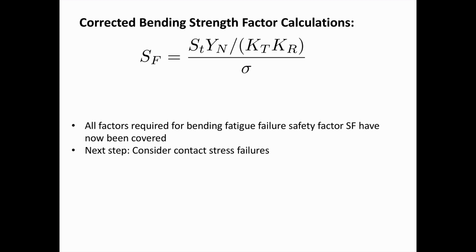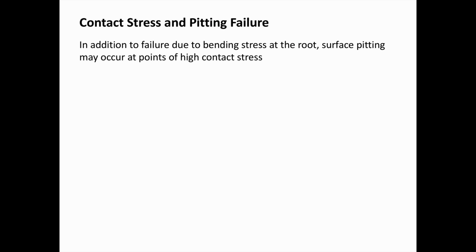And now we're going to look at contact stress failures. Let's look at contact stress and pitting failure. So in addition to bending stress at the root, surface pitting may occur at points of high contact stress, and we talked about earlier how this tends to be where the tooth surface intersects the pitch diameter.